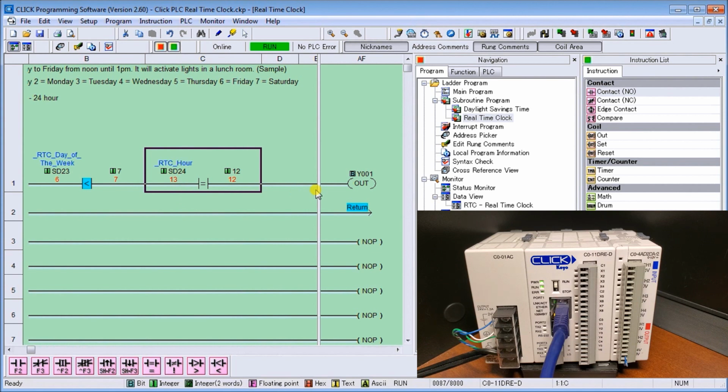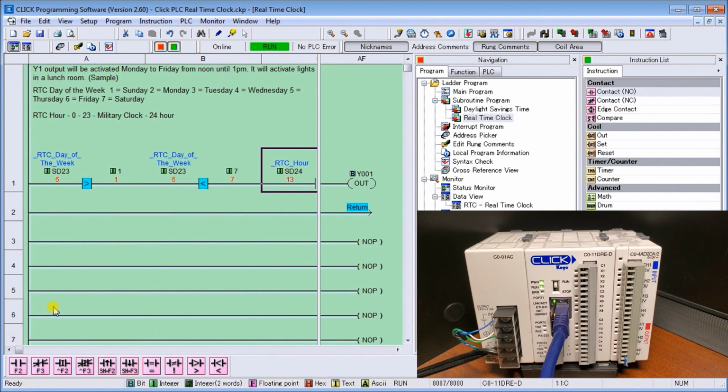So that is our real-time clock. And the real-time clock in the controller is actually good for about plus or minus 60 seconds for a month. That means that we can be out a maximum of about 12 minutes a year when we look at this unit. So we have to come in periodically and adjust it. Now typically what I see is anywhere from 2 to 3 minutes a year that it is out. So they're giving you the maximum amount that could actually be out.